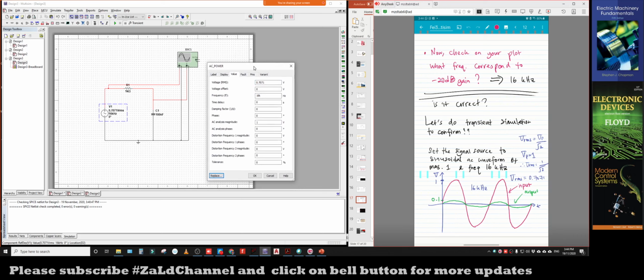Okay, so basically, students of electrical or electronics should already know how to calculate this RMS value, right? RMS value is different to the peak value. If we specify the peak value Vp as 1 for the input signal, to get the root mean square value of the voltage, you can just use this equation, which is Vrms equals Vp divided by square root of 2, right?